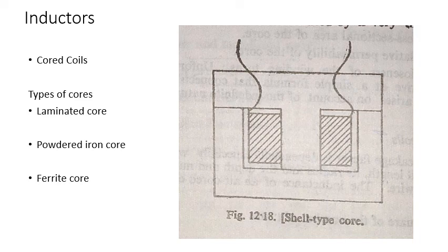Right? So the ferrite core is what? It is a ceramic material that provides high values of magnetic flux density, but it is an insulator. Therefore a ferrite core can be used in inductance for high frequencies with minimum eddy current losses.